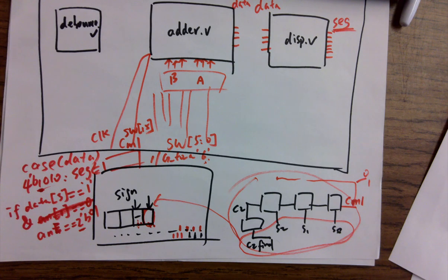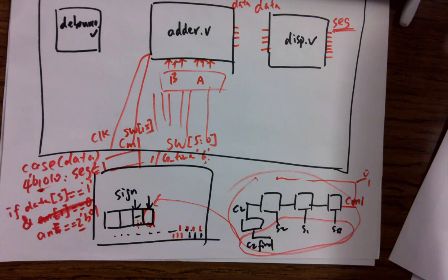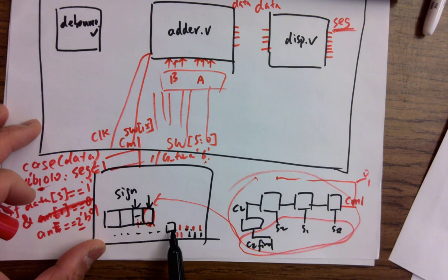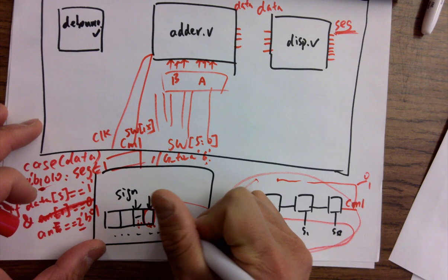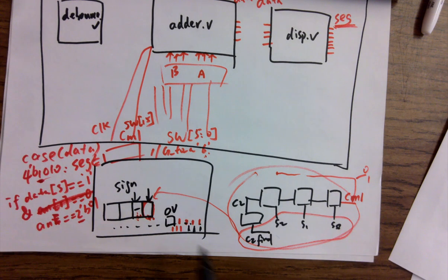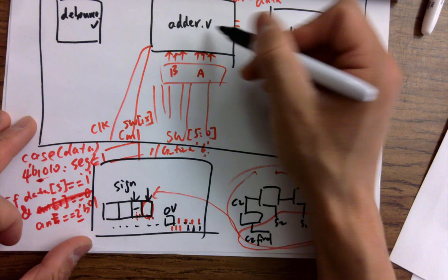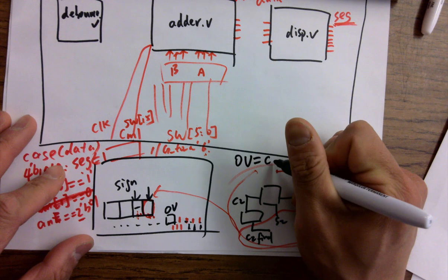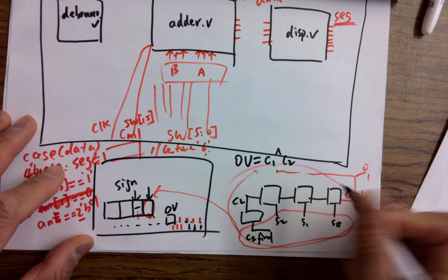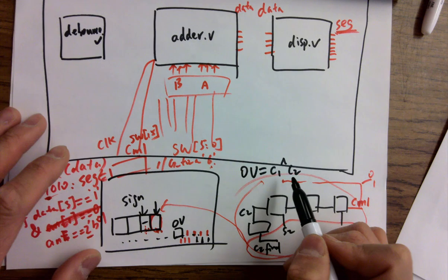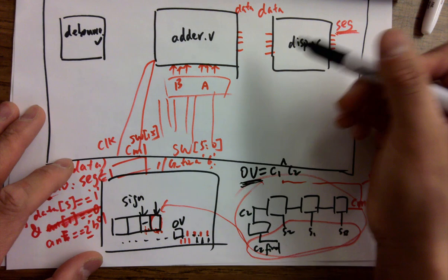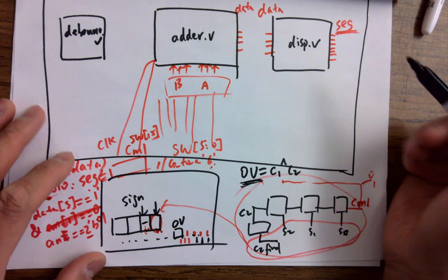That's probably everything, right? Oh, another bit I want you guys to display is over here. For the 5th bit from the right hand side, this should be the overflow bit. If it overflows, this one should be on. So the adder's overflow bit, we know that OV equals C1 XOR C2. This is what we got from Tuesday, right? So we definitely know that the adder will be able to output OV, so we don't have to output it to any other modules. We directly output it.